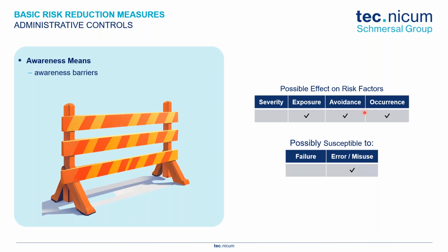But did you already try engineering controls? You have to go through the process and exhaust the previous options, and of course you have to document and justify. You have to justify why you didn't do some fixed guarding, why you didn't do movable guards with interlocks, how come you didn't add any safety functions like light curtains, safety mats and scanners. Why are you relying on just awareness barriers?